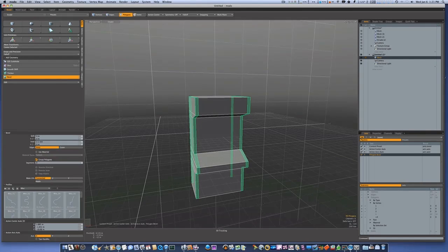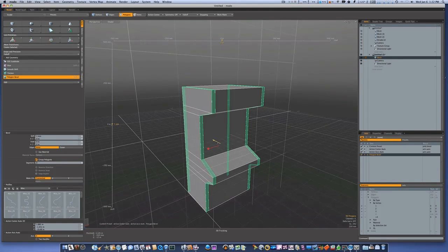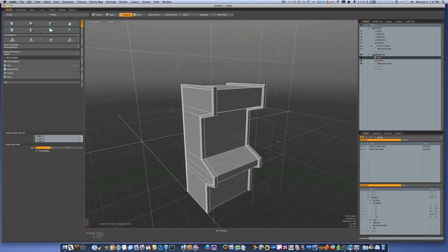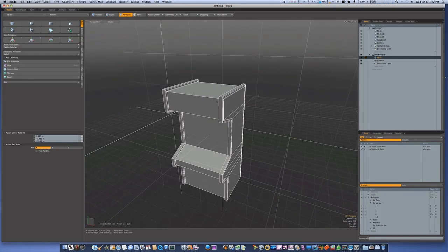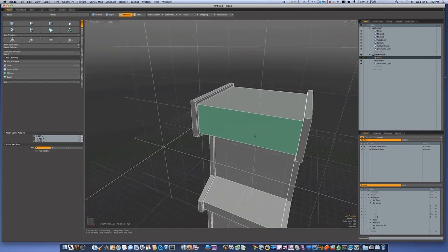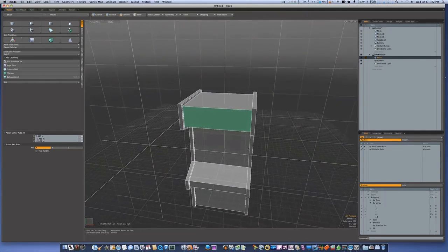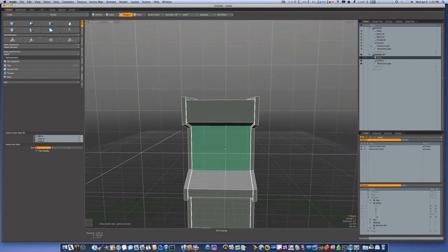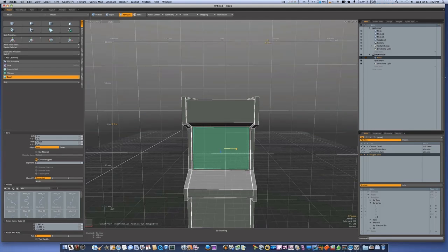Let's hit our bevel key, and click once in that tool to activate it. Now let's pull on our blue handle till it comes out a little bit, just a little bit. Then let's shift click to reactivate our tool. Let's pull out some more, shift click, and pull out some more one more time. The reason we shift clicked is, as you can see, as we've done that, it laid in our loop slices for us, and we don't necessarily have to go back and do that now. Okay, now we have this. Let's go ahead and bevel in our screen like so. Shift click, bevel it in.